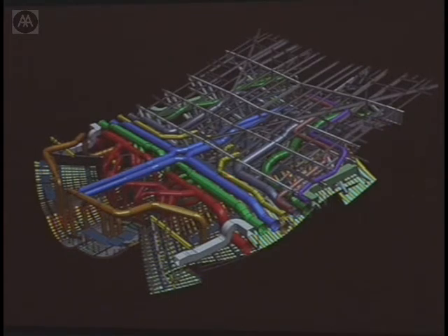What does that mean? That means that when you install this stuff, you have to install it at the same time as you're installing the brace frame structure for the roof of the hall. This is a primary steel. Some of it's turned off here so you can see this stuff. But basically, you can't weave it in afterwards. There's literally no way to get that stuff inside.